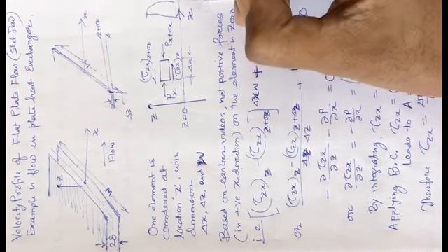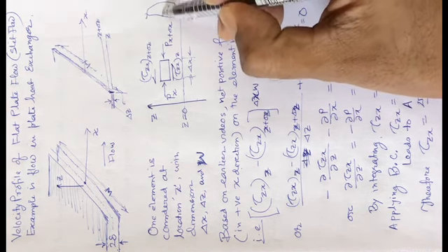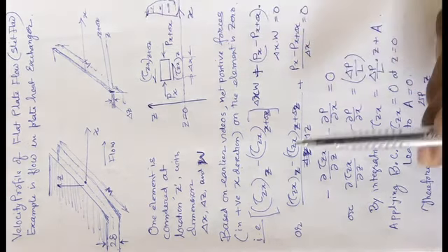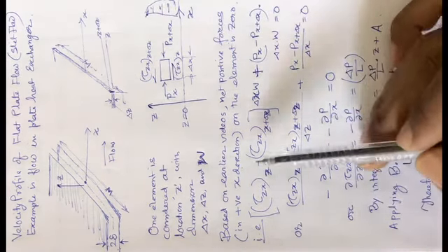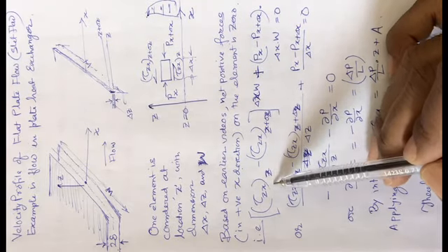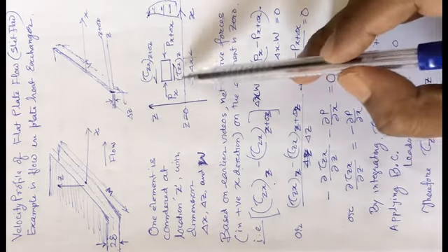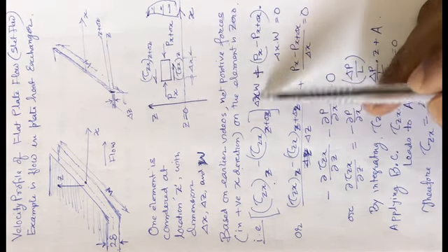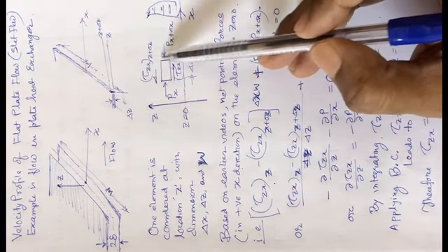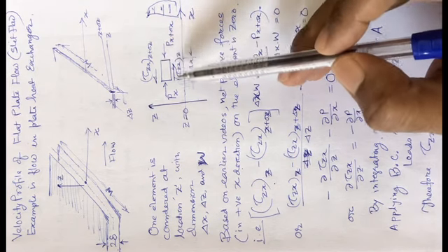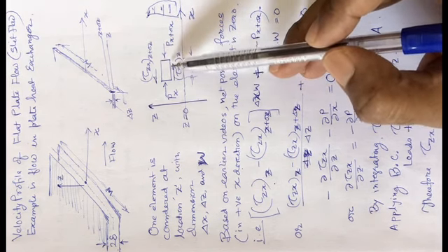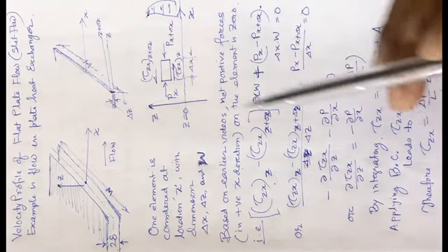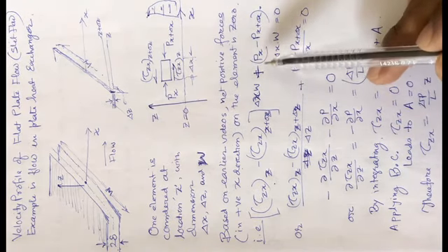Means near the center it will be higher, and near the top surface it will be 0. Okay, therefore, actually see what we will be saying: the positive directional force is this particular value minus this one, which is in the negative direction, multiplied by this height. Sorry, it is for the shear stress only, so this length multiplied by the width across this plane, that is delta x into W.